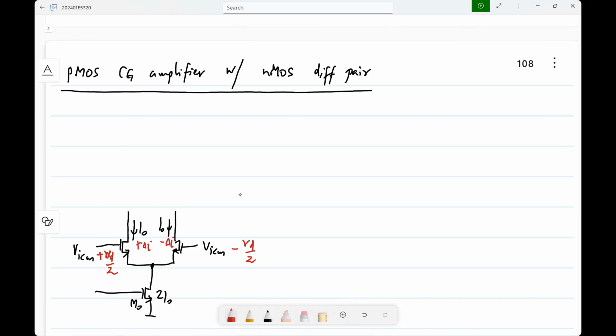Earlier, we had the bias current plus the increment, and the entire thing went through the NMOS common gate device. So the operating point current for the differential pair and for the common gate device was the same. In fact, even that is not strictly necessary. You can make them different if you really need to by adding current sources and so on. But now we have to do that.